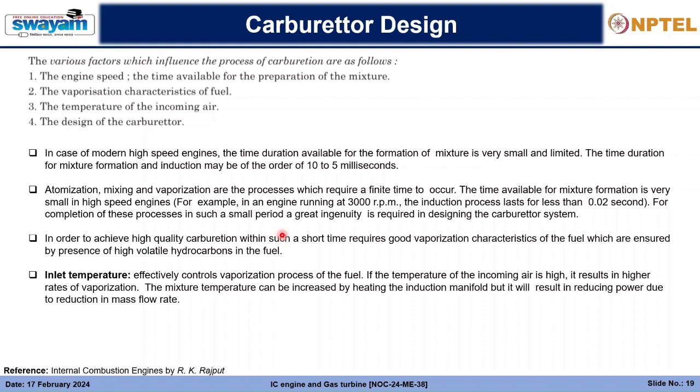Then inlet temperature also affects this. If the temperature of the inlet manifold, where the fuel droplets are released, is high, then the fuel has a higher tendency of being vaporized easily, right? So that also affects the vaporization process.